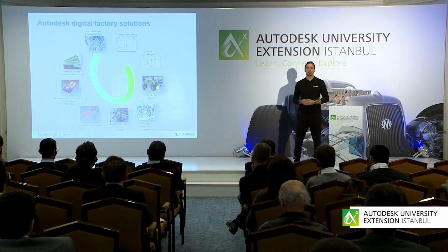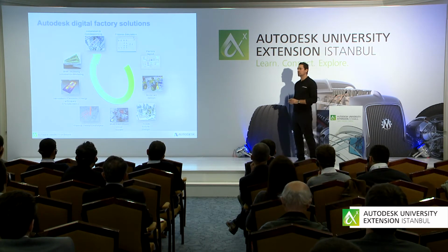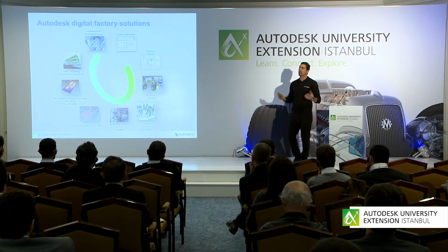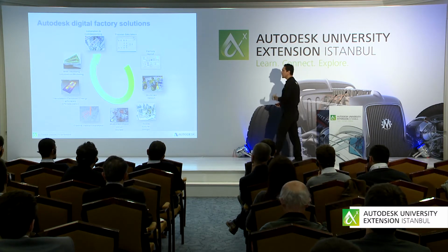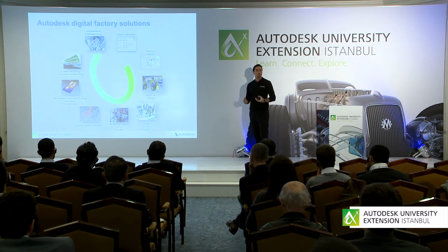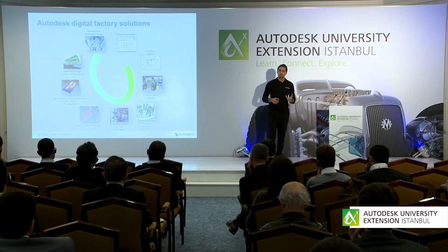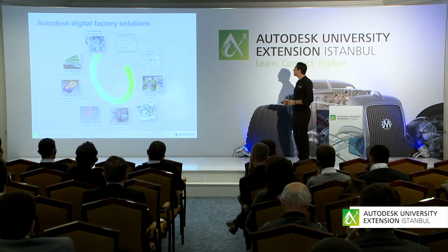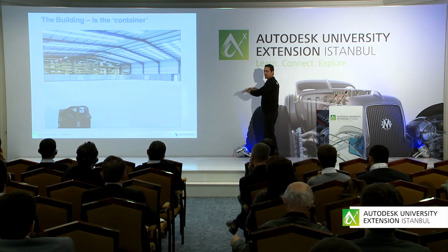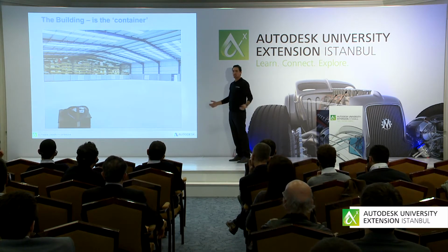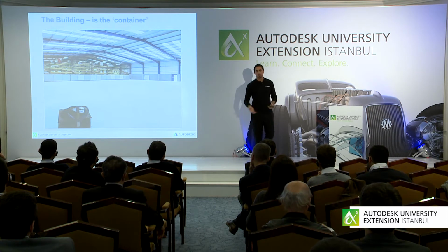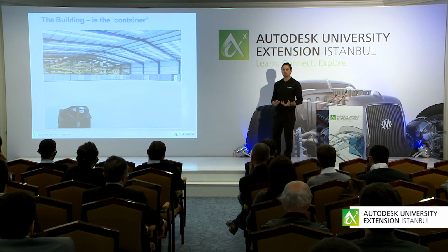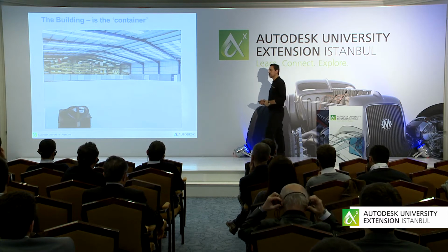And you can get into some more advanced areas of, now I have a factory, I've got all these machines set up that are producing X amount of components. How much energy is coming off these machines? Maybe it's a component that you've got to keep under a certain environment, a certain temperature. And this is where we can use CFD to simulate that environment and the heat dissipating into that area and understand what the thermal load is and what it takes to cool that environment down to keep these machines operating at an optimal level. So the building that's inside is just a container. It's a big box. What do we do with this big box? We have to set it up so it's actually simulating a factory layout.